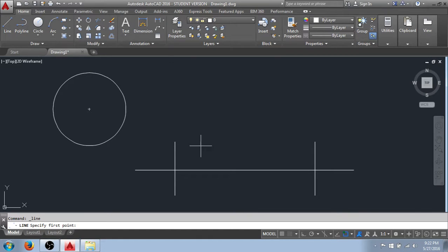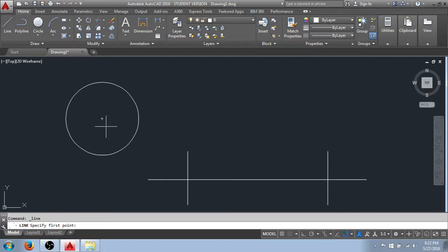and you'll see that now these object snaps are available to me when I get close to that area of the graphic object. Here's our center. Here we can see our four quadrant points on the circle. There's our end point and a midpoint and an intersection.